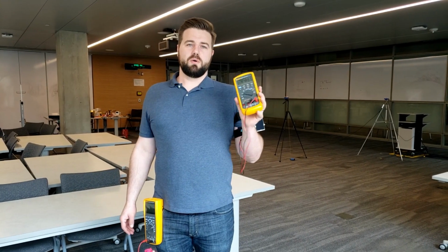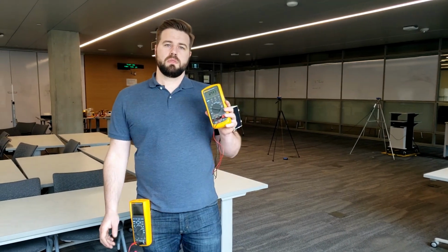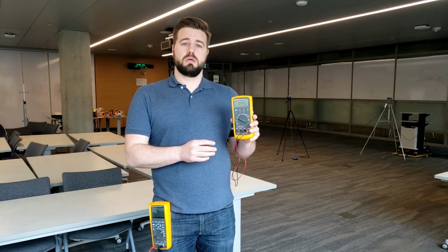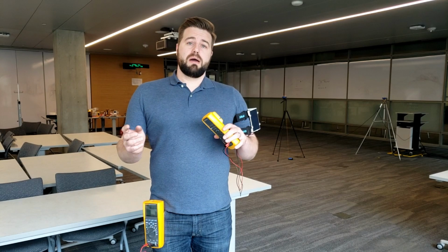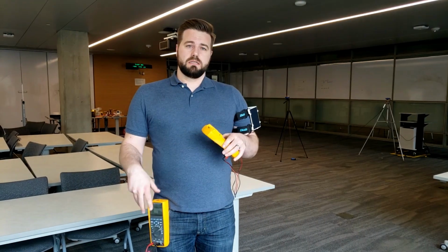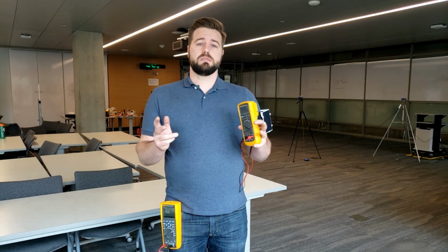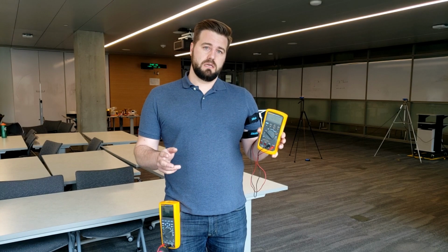Hello! So I'm covered with voltmeters because I am showcasing our two energy harvesters. The RFID chips that we chose can either be operated in passive mode, in which case they're being powered only by incident RF signal, or they can be powered actively. And the benefit of that is when we hook them up to a battery, we reduce intermittency problems, because of course they have a constant power source, and secondly, we can increase their range because their sensitivity is increased.